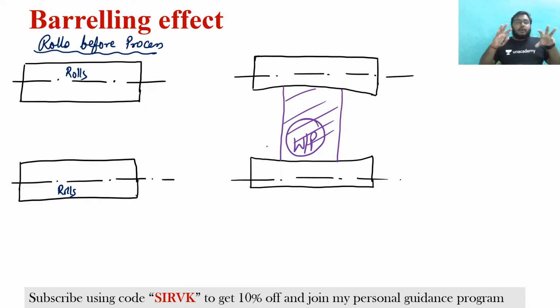Since this rolling operation is continuously carried out, at this point we can see greater forces are acting. Due to these forces, what is happening? This roll is deflected towards the middle. It is deflected in this direction.